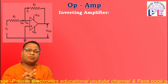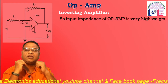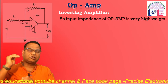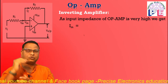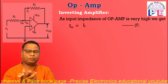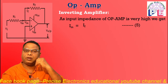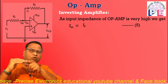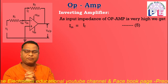And the input impedance of the op amp is very high. In case of an ideal op amp, it is infinite. So as the input impedance of the op amp is very high, the input current must be equal to the feedback current. So I in is equal to IF, that is our equation number 5. I in is equal to IF, because the impedance of the op amp is very high, therefore the input current is the same as the feedback current. That means I in is equal to IF.